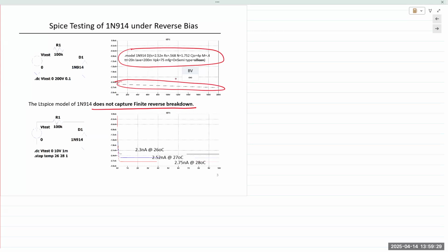We can see it. So let me add the diode this way. And then, of course, this is the power supply. Simply applying positive to the cathode. So it's reverse bias, but when LTSpice plots it, it thinks it's applying a positive voltage. So what is being shown as the first quadrant is actually the third quadrant. It's negative voltage and negative current. The graph is just flipped.